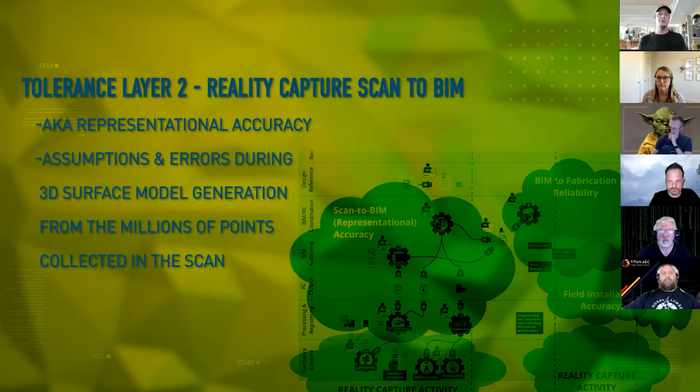So anytime somebody says you don't have to level the scanner, what you need to then immediately append onto the end of that sentence is, if you don't care about accuracy. Good news is IMU-based scanners, if you level them very well first, they do a much better job. So their accuracy is relative to how level they are. So you can get good accuracy out of one, but you have to level it really well. So get really good at that if you buy a cheap scanner.